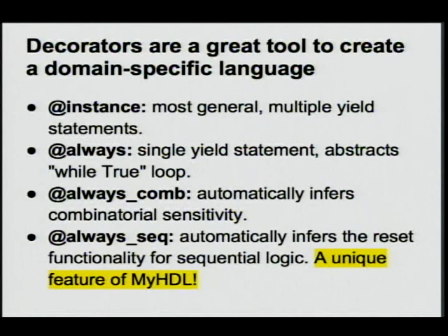The reason why I went into all these details of these decorators is to give you the message that decorators are in fact a great tool to create a domain-specific language, which MyHDL in fact is. They are really building blocks that create these little languages within Python that do the things that you want. I repeat all these decorators here: instance, always, always_comp, always_seq. All of these have their purposes. They're not there just because someone asked for it. They are all heavily used.